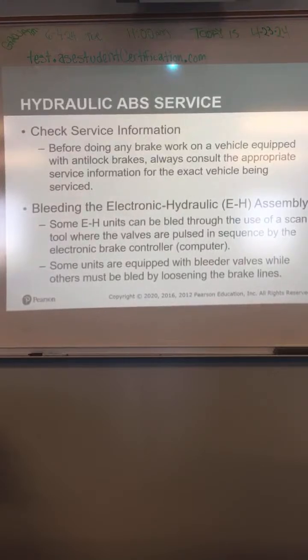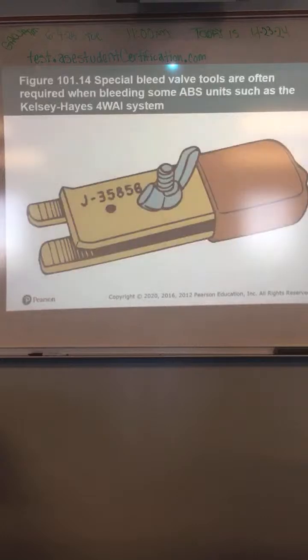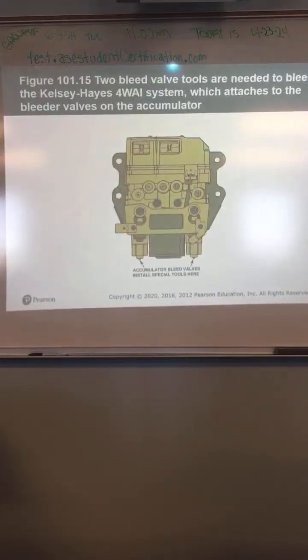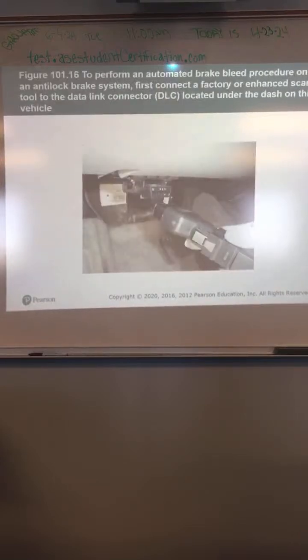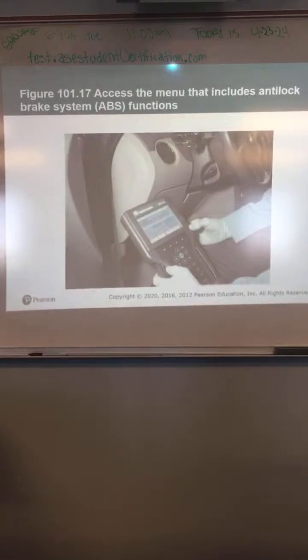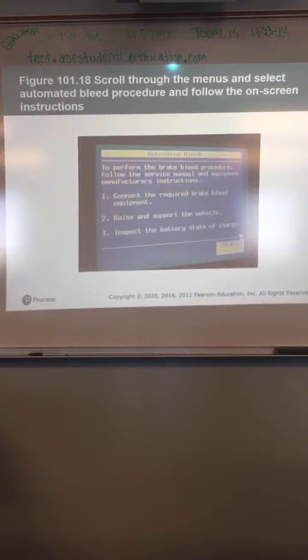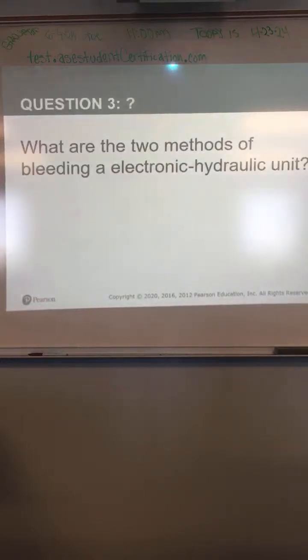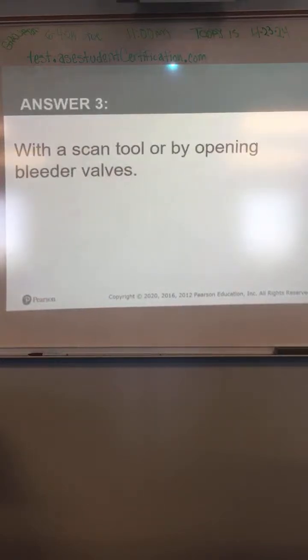Some units are equipped with bleeder valves, others may require loosening the brake lines. Again, special bleeder tool for an ABS unit. Scan tool, just use automated bleed in this case. It's going to give you on-screen instructions on how to do it.